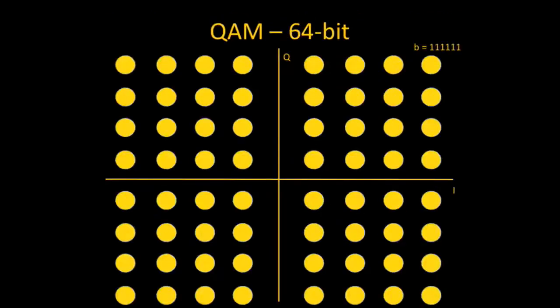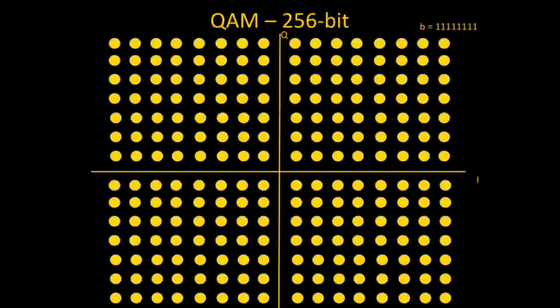But as we keep rolling this out, 802.11n stopped at 64-QAM, right? So that's quite a few targets. In this case, we can send six bits per symbol. So there's a fair bit of density in terms of the bits we're sending across each symbol. But if you look at 11AC, it's 256-QAM, right? So it's very precise. You have to be archery masters, maybe even from the front row, to hit targets that are this close together. And so what this means is you need really high signal-to-noise ratio. We'll talk about some dB math, but essentially looking at SNRs of around 40, which results in signal strength of around 50 that your client hears. So in realistic terms, if you're beyond 15 feet from your access point, you're probably not getting a signal strong enough to demodulate 256-QAM.